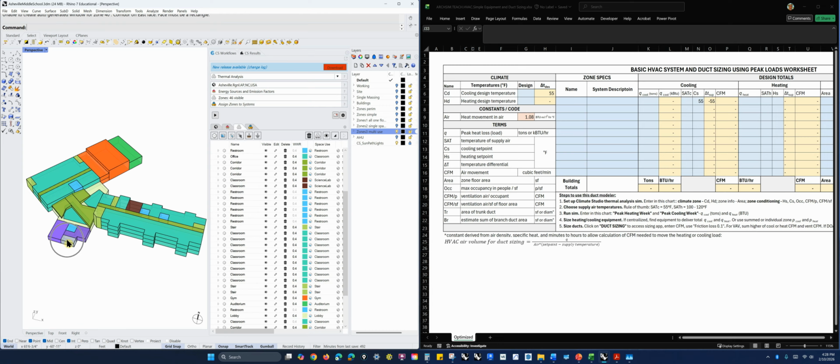You have a boiler in here, and then you need to have either water, or with a boiler, it would have to be water, but something that's very small and can move all of it, because you need to get water to here, here, here, here, way over here from this one source. And then you can insulate those pipes really easily. It's an efficient way of getting that heat to a position.